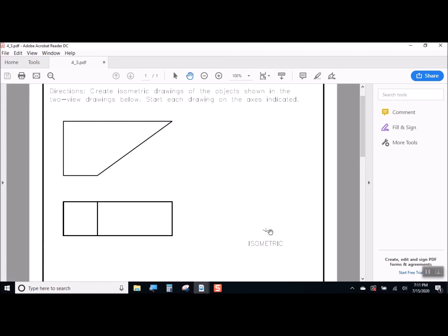See, the shape is not the front view, the shape is the top view. So when you are laying this out, keep in mind that this corner, if this is the width, and this is the height, and this is the depth, well, that's the starting point for the width going this way, the depth going that way, and the height going this way. But the shape will not happen in the front view, the shape happens on the top view. So you'll be working on the shape, and the shape will be visible from the top, not from the front or from the right side.